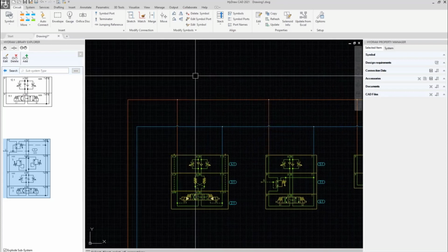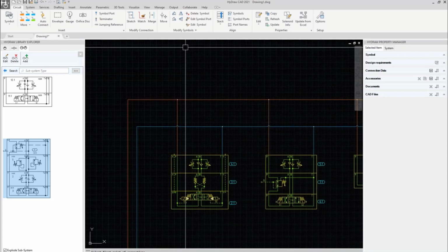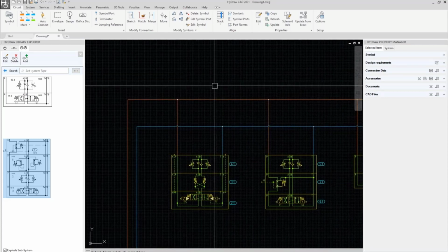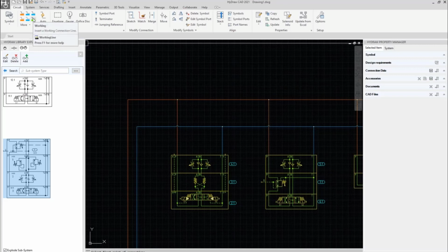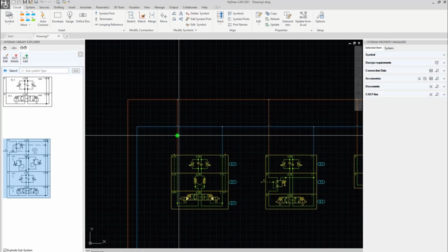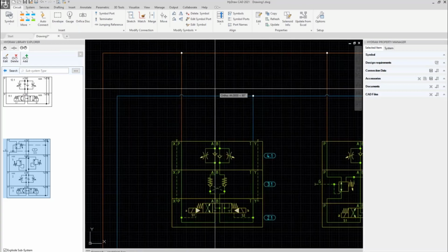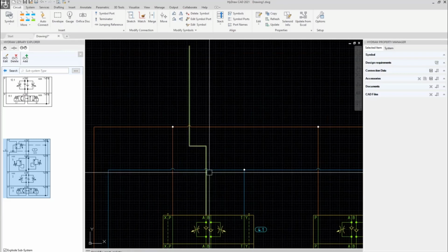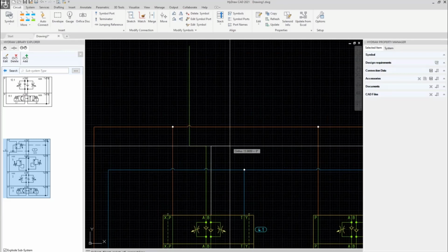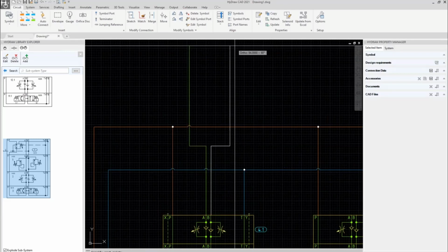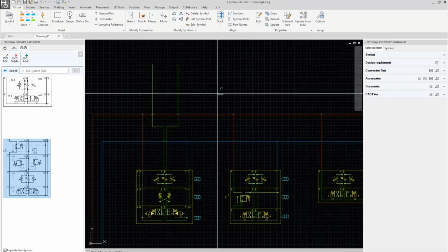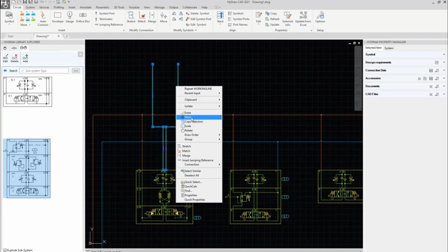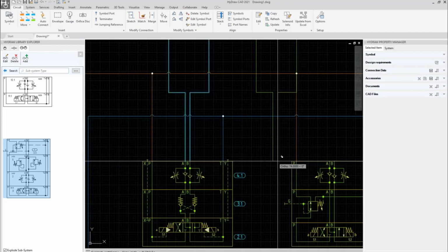Now we make working lines. According to ISO 1219, working lines have a different color. They belong to a different layer, and we have the working line. And we start from A. And let's say that on top we will have a cylinder, so let's extend a bit. We could also copy entities, so using the AutoCAD functionality copy, and we start from B and paste.